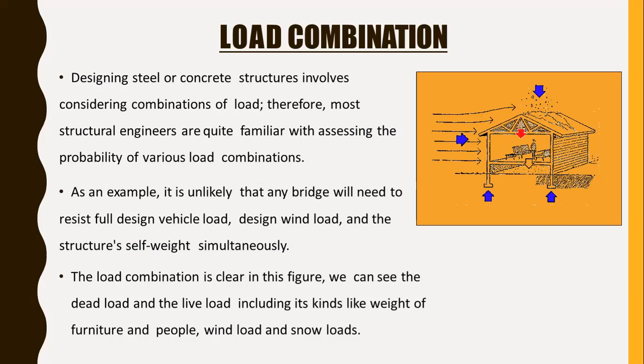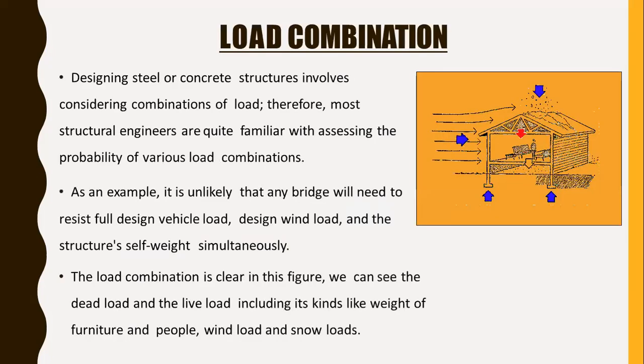Load combination is clear in this figure. We can see the dead load and the live load included, like the weight of furniture and people, wind load and snow load. So consider the design as dead load plus live load plus wind load plus earthquake load, right? These load combinations are important for us. So here we added our chapter, the first one, which is the introduction, meaning loads and load combinations.